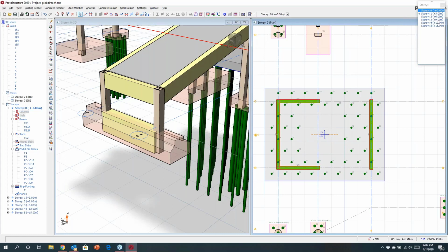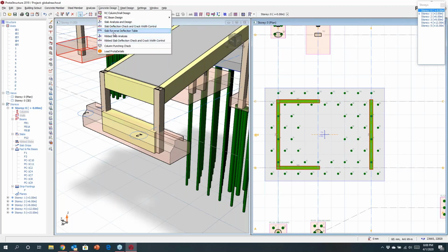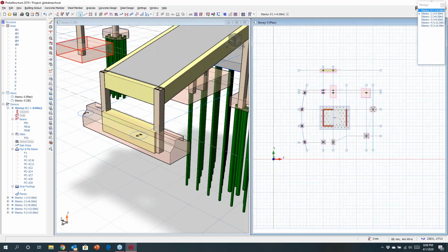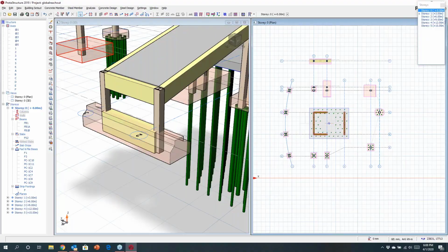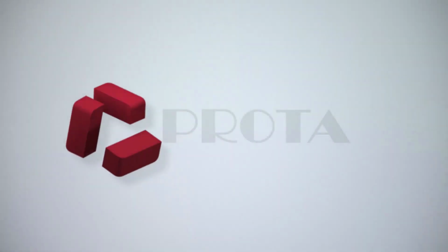to suit. Now once we've done this, and I won't go into it just in the interest of time, but you can move in at this point and run an FE raft foundation analysis. You can cut integral strips through for the design of the reinforcement, and you can also perform punching shear checks here as well. So all of this can be done within the foundation model, and this gives you the ability to be able to design quite a wide range of different foundation systems.